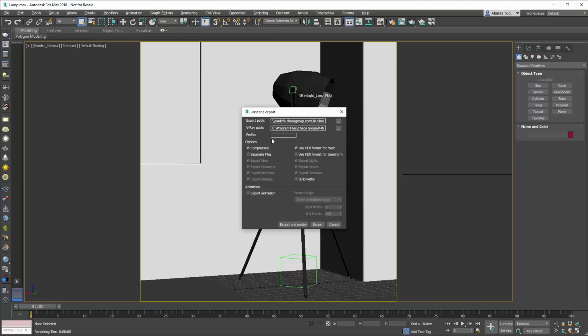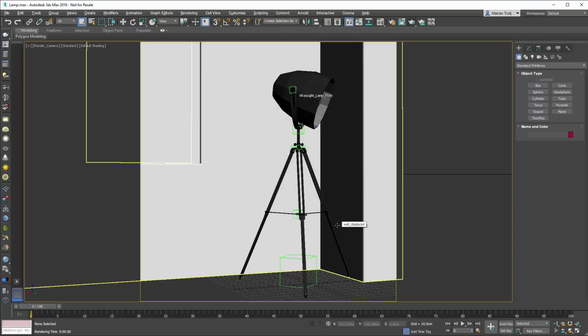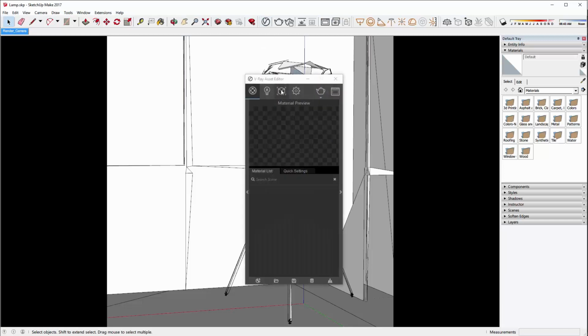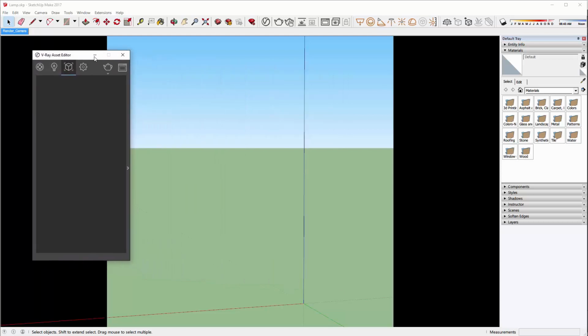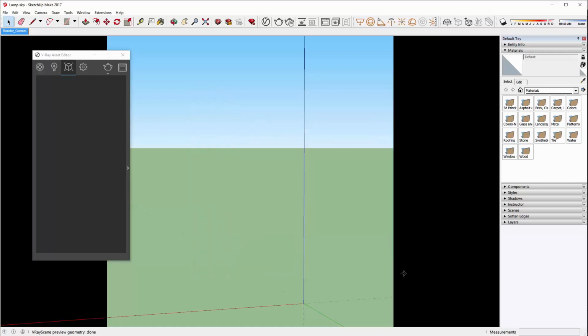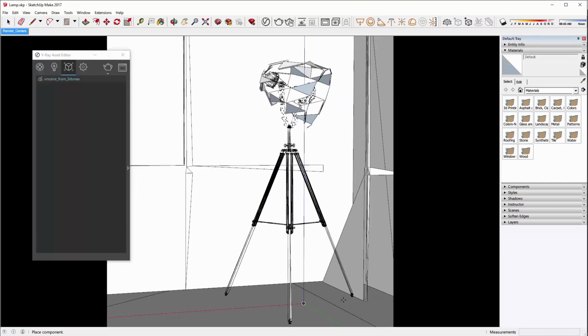And we basically make sure to save the scene in the location. So we export a file path. And then we simply click Export, and the scene will be exported somewhere on our hard drive or the network. And then when we go back to SketchUp, we can find it. I'm going to delete the old one and just open a new one. And then when I click at the origin and hit escape, I'm going to have the new scene imported.